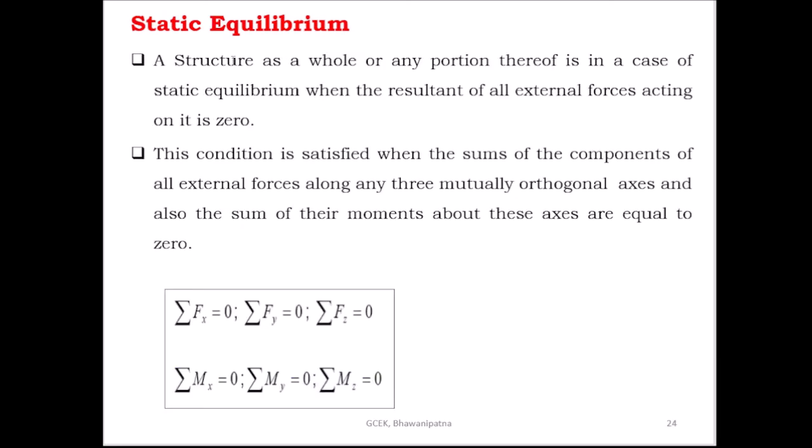Then coming to the condition of equilibrium: in order to apply the principle of statics to a structural system, the structure must be at rest. This is possible only when the sum of the applied loads and support reactions is 0, and there is no resultant couple at any point in the structure. In this situation, all component parts of the structural system are also in equilibrium.